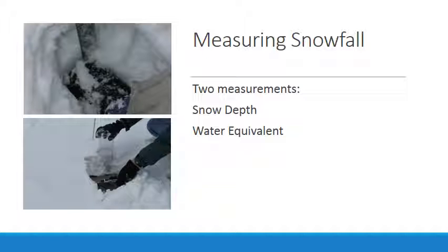To measure the mountain snowpack, which produces 75% of the water supply for the western United States, automated weather stations employ snow pillows that have been installed at more than 600 sites. A snow pillow consists of 2, 3, or 4 large panels that measure the pressure exerted by the weight of snow that collects on them. Because snow pillows have large surface areas and measure the water equivalent of snow, they provide a good estimate of the volume of precipitation, which is really what we are after.